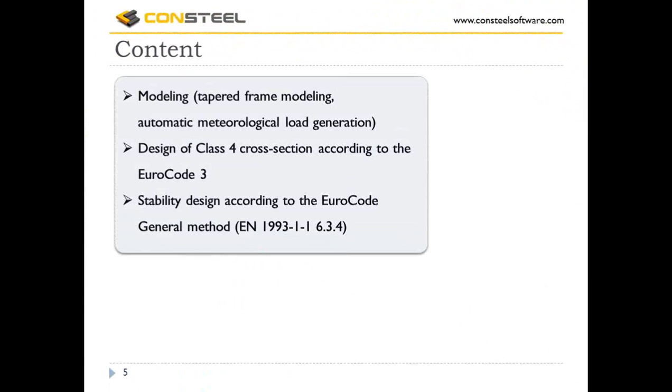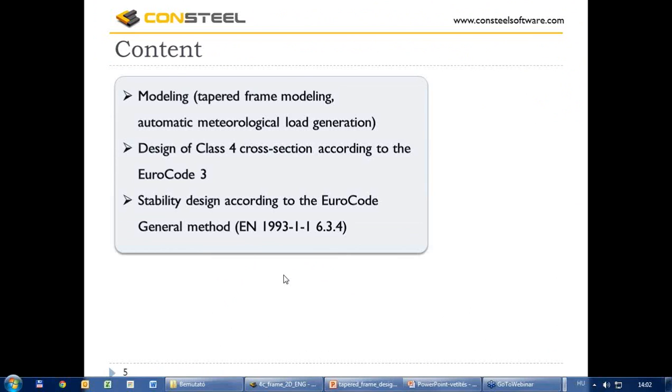Today's webinar content will be the following. At first I will show you the modeling of a tapered frame with 2D meteorological loads generation. Then I will show you the class 4 cross-section design in ConSteel. At the end, I will demonstrate the stability design of the tapered frame with the EuroCode general method.